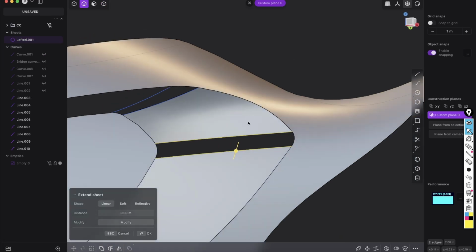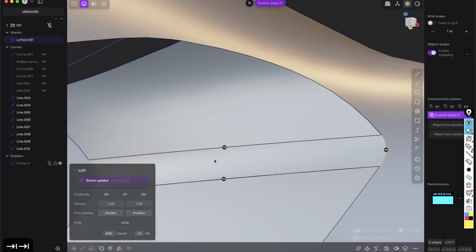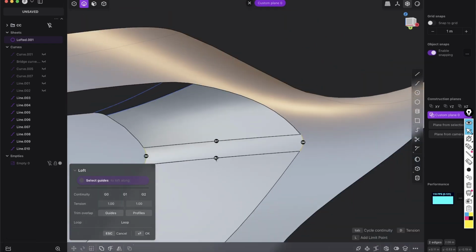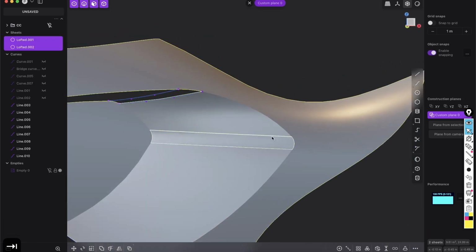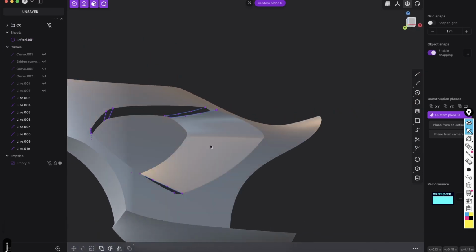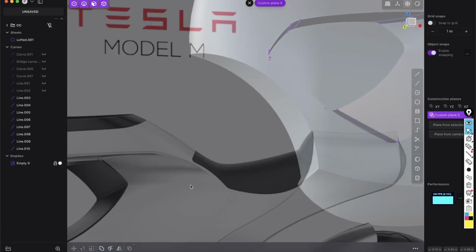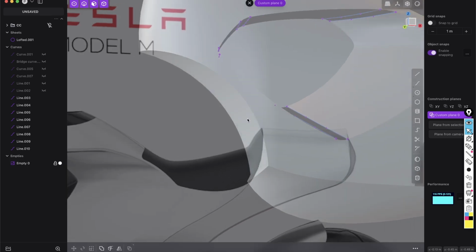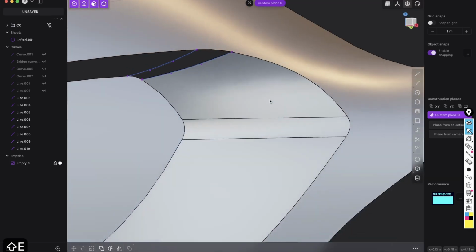And now let's try to loft those faces, shift, again, tap, so it's everywhere G0. But here where we have this smooth surface, we want, most of the time, G1. So we have continuity, so it's smooth. And if we join everything, you see we get a pretty nice surface as we have here. But again, it's the quick solution.